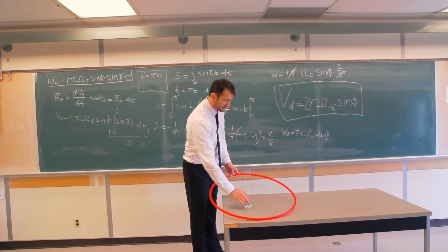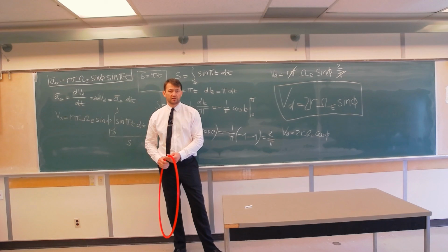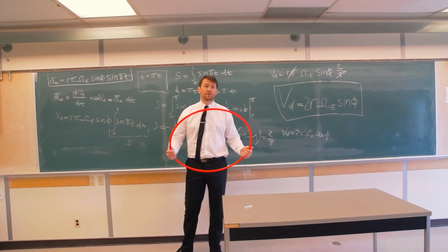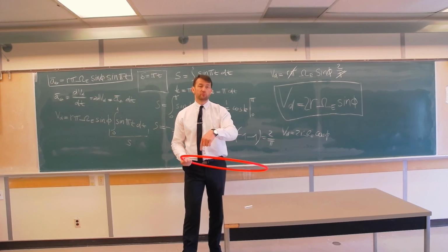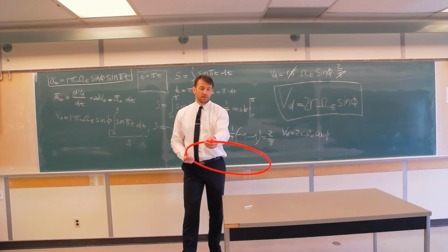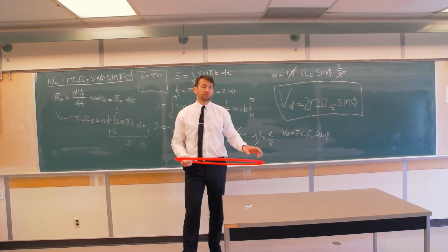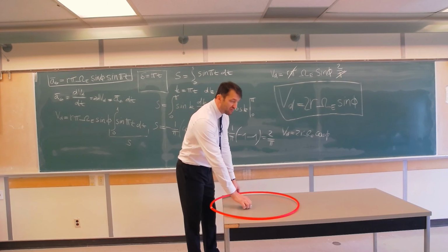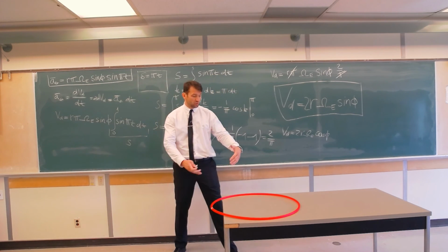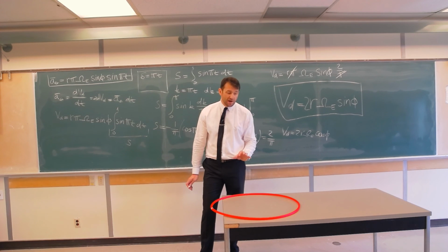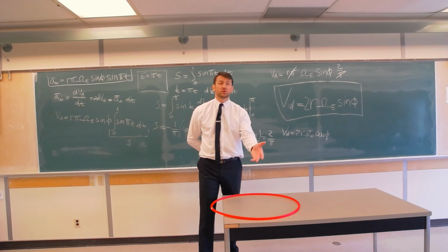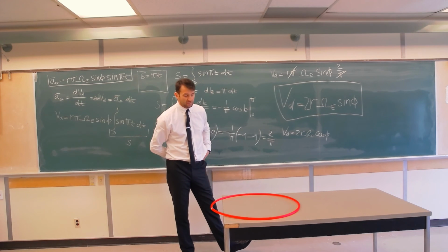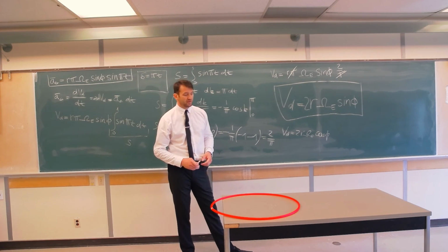What else should I say at the end of this video? It's already very long. Of course, there are many assumptions that entered into this derivation. One assumption is that there is no friction. Of course, when the water starts moving around, there is friction with the wall of the tube, and we didn't consider that. So if you are to perform this experiment, what you want is to measure velocity in the center line of the tube, because then you are at the furthest distance from the wall.